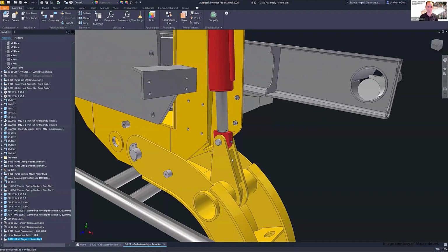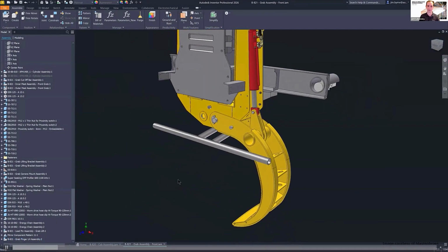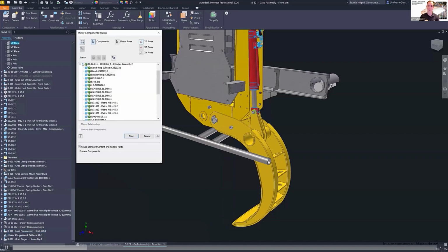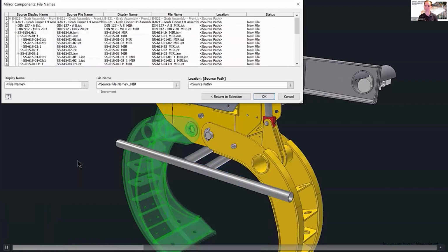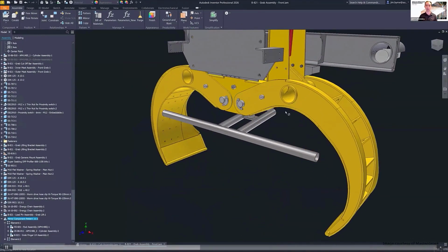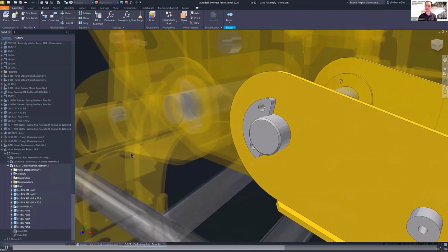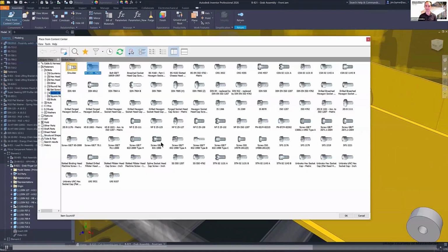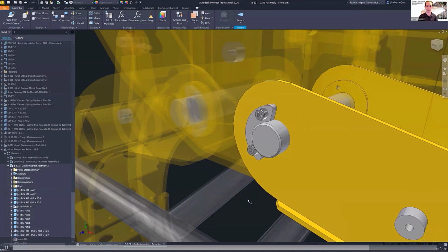And we also just wanted to take a note beyond the smart mirroring. It's just a powerful control and flexibility update. So you can now suppress mirrored components individually, really fine-tune your design views and positional representations, and manage how mirrored parts appear and behave all from the source. So this also works with iProperties and styles seamlessly. Those mirrored parts inherit everything that they need, including sheet metal styles, design intent, all while generating their own part numbers, which can be super important for these assemblies.